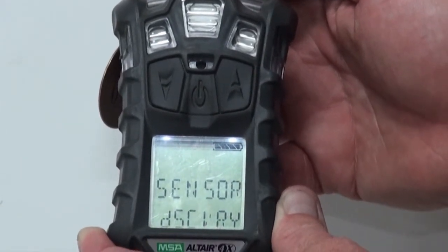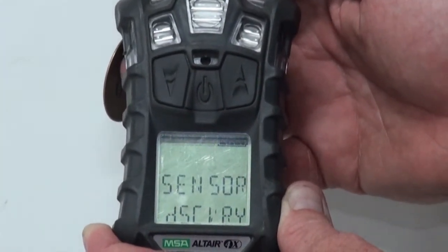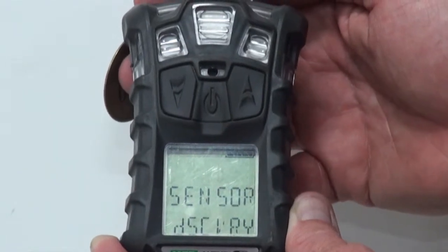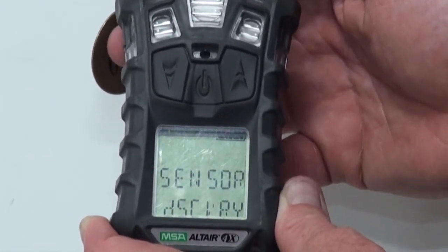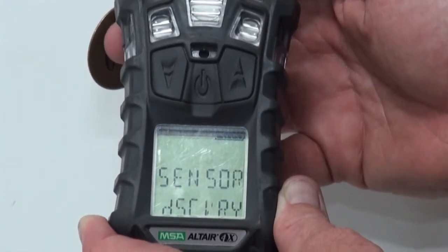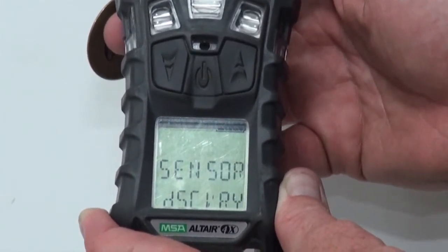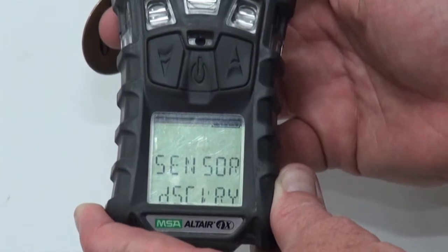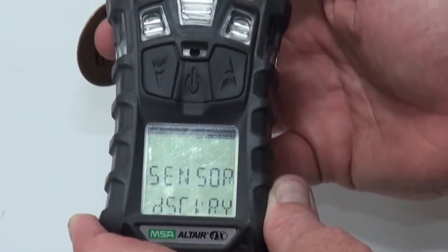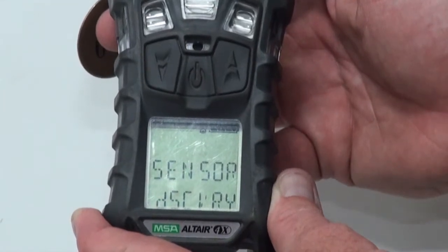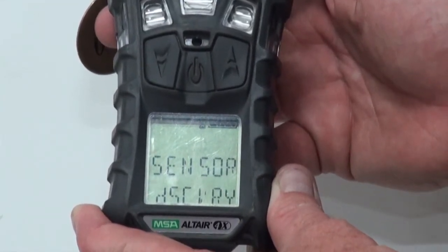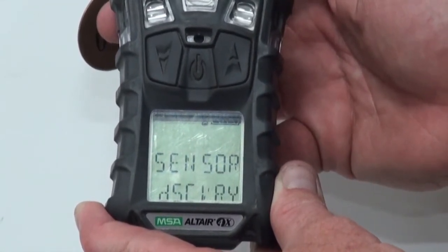self-check. It's going to analyze the sensors, it's going to tell us what the low alarms are and what the high level alarms are. We should validate all those numbers to ensure that they're within the desired ranges that we want the monitor set up for. When the monitor is thinking or processing through systems, you'll typically get an hourglass or a time clock indicator to tell you that the monitor is in a working mode.